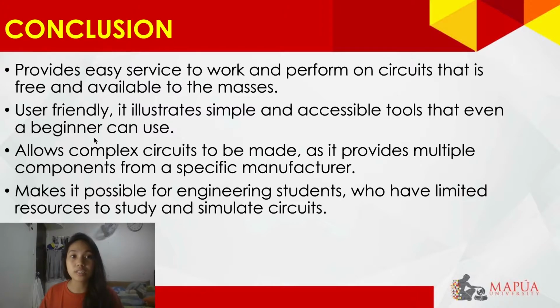And thirdly, for the conclusion, it allows complex circuits to be made as it provides multiple components from a specific manufacturer. An example of this is a capacitor. You can right-click a capacitor and go to its advanced settings and pick a specific model that you would like it to run. The same can go with a diode. There are specific diodes you can pick through as well.